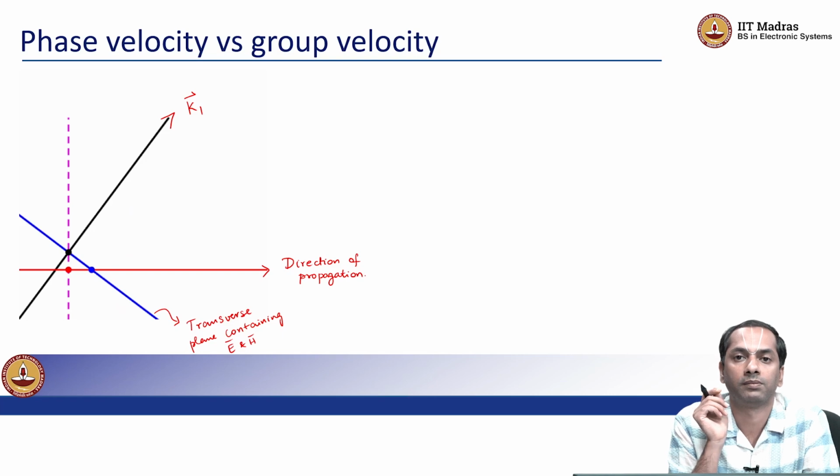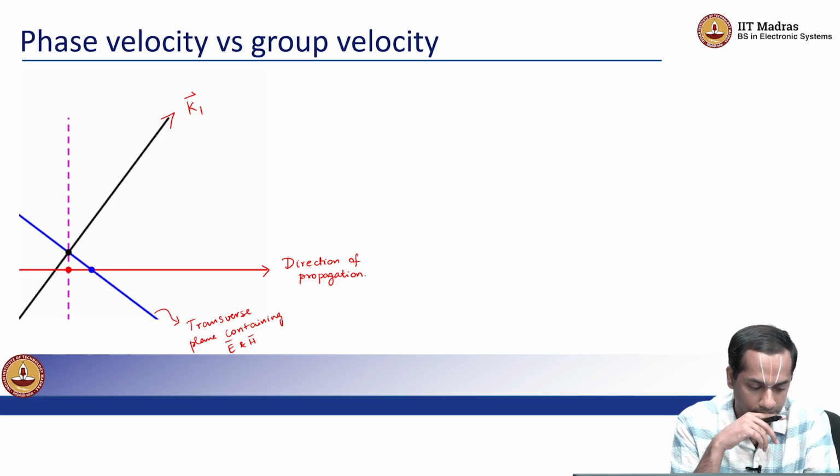Okay. So remember that I can picture the modes in a parallel plate waveguide as essentially the summation of two plane waves in an unbounded media, but the angles or their directions are very carefully chosen based on the frequency of electromagnetic radiation and the distance between the parallel plates.